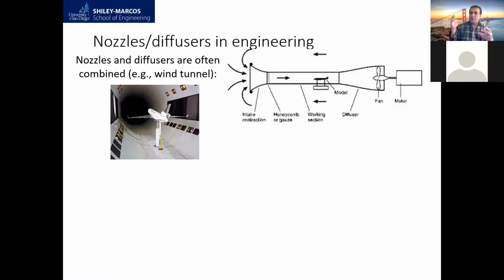So when you send the air through that conduit, we need to measure the pressure or velocity or temperature and so on. One method that we use in the laboratory to determine all those properties, we call it the pitot tube. The pitot tube is going to give us the information about the velocity.